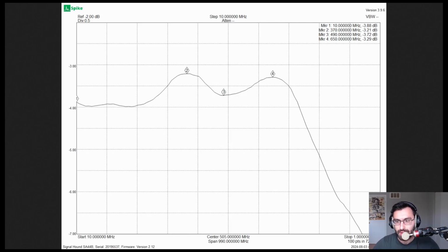An editor's note: the reason you don't actually see this show up in the other tests is because of the Nyquist frequency of the ADC. In single channel mode, you basically get 500 megahertz. So you capture a little bit of that first peak, but it's not really that impactful in terms of what we can see. That's also because we're not using sin x on x interpolation here. We're using linear. And that's also why I did not use the rise time to bandwidth calculation, because that's invalid.